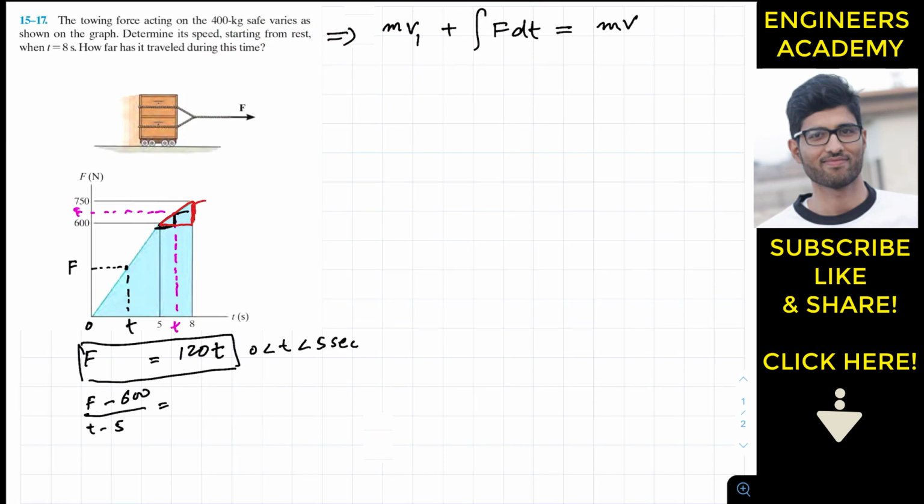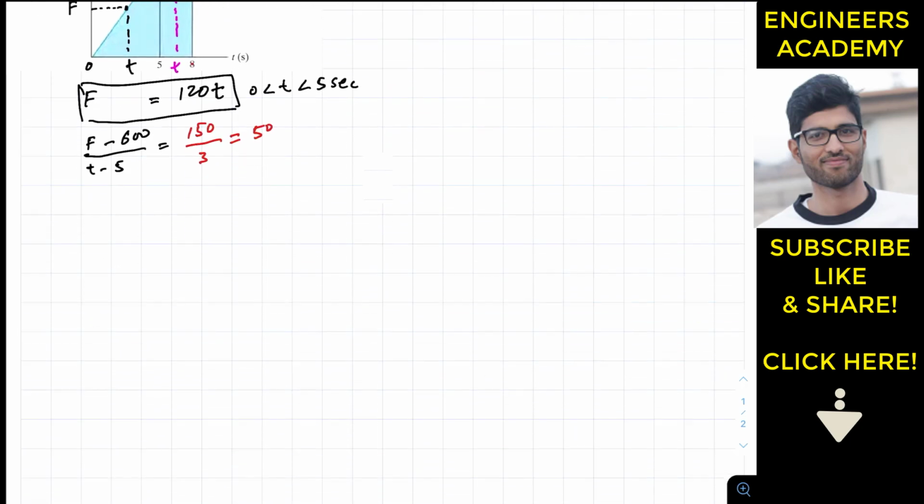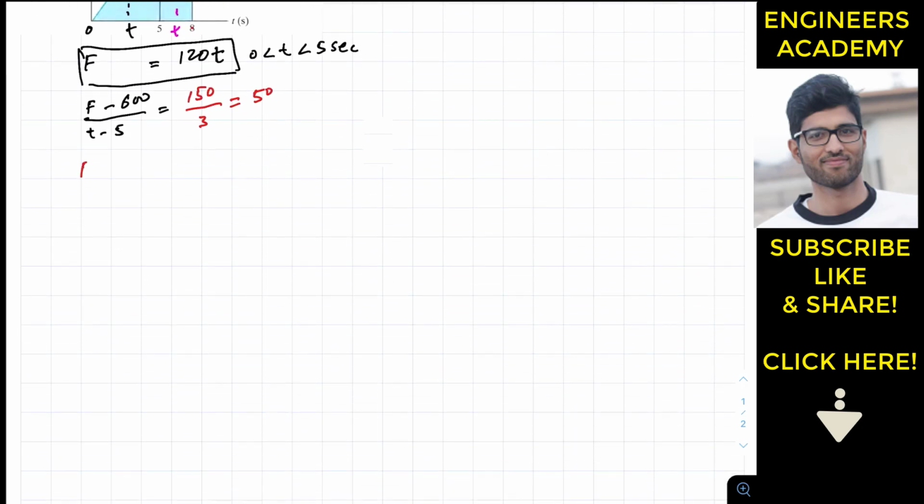This height will be 750 minus 600. So 750 minus 600 is 150, divided by this base. This base is 8 minus 5, so that is 3 seconds. And 150 divided by 3 is 50. From this equation we can write that F minus 600 is equal to 50 times (t minus 5).